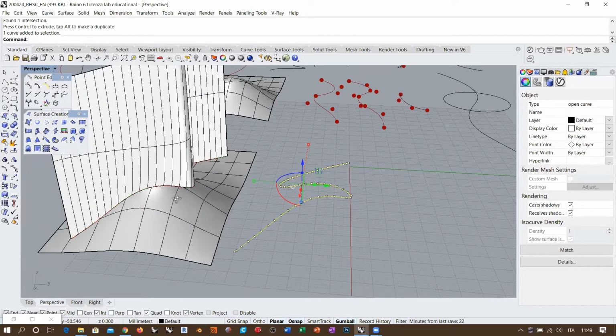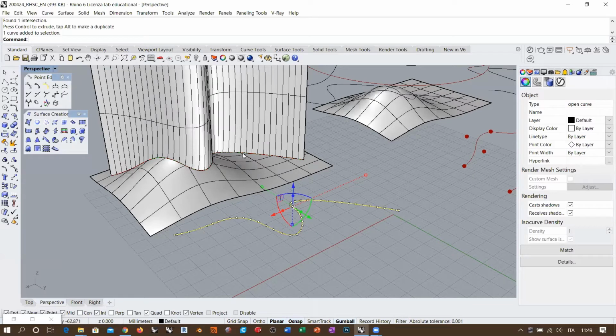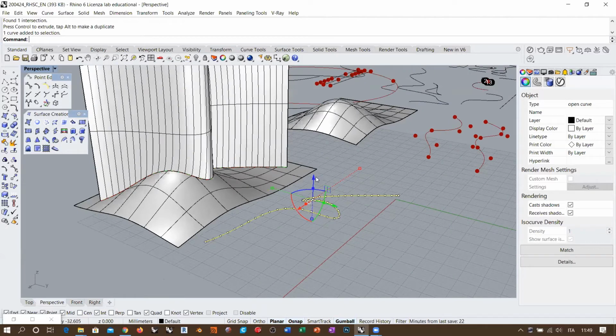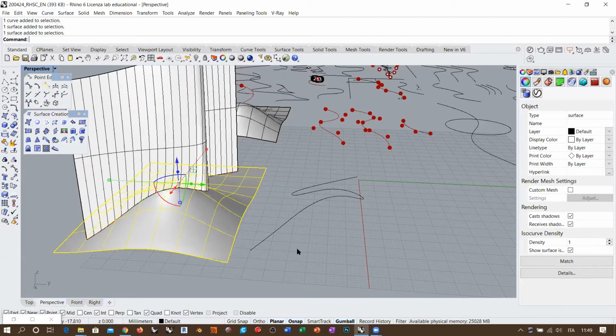Eventually, there is a maximum deviation of 0.007, but this level of separation happens in a very localized spot along the curve. Obtaining a maximum deviation doesn't mean that whole portions of your curve have that separation. If that value only involves a specific spot of the curves, then you still have enough precision in the coincidence between this surface and this object here.